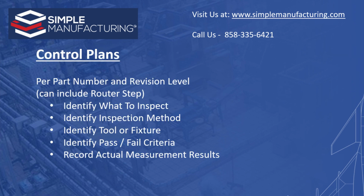Also included in this module are control plans. The control plan is used to identify inspection specifics, provides exact details of what to inspect, the inspection method, the inspection tool or device to use, and the pass and fail criteria. When using control plans, inspectors have the ability to enter the exact measurements obtained. Having these measurements help businesses identify any unfavorable trends or out-of-control processes.